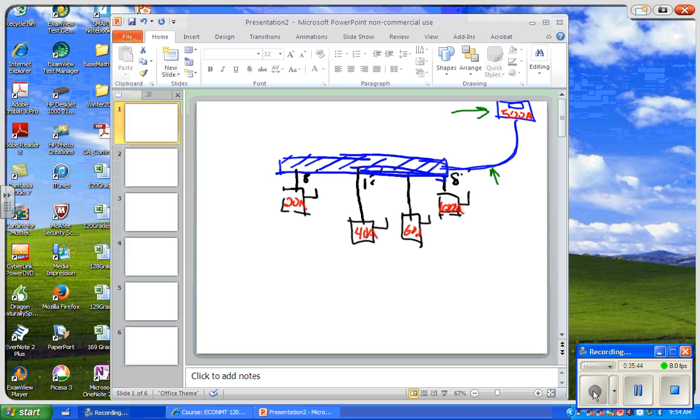No, that's not what they're talking about either. They're talking about the ampacity of these wires right here called tap conductors, and they're related to the ampacity of the overcurrent protection device. All right? Now, that means that these wires have a minimum ampacity if they're under the 10-foot tap rule. They must be at least 50 amps. 10% of 500, 50 amps.